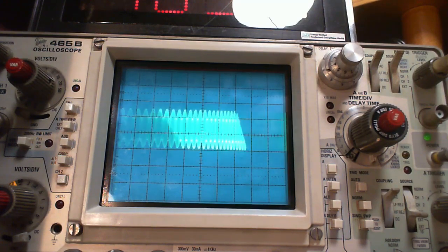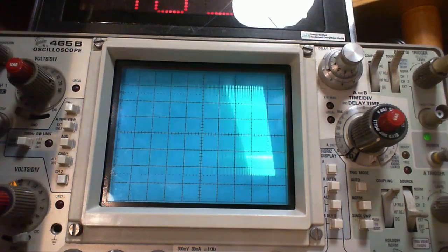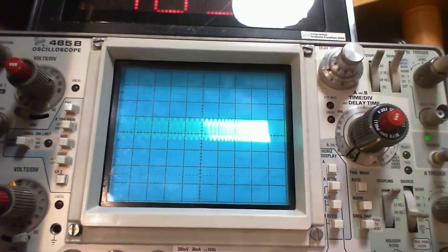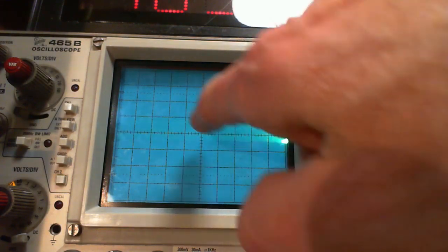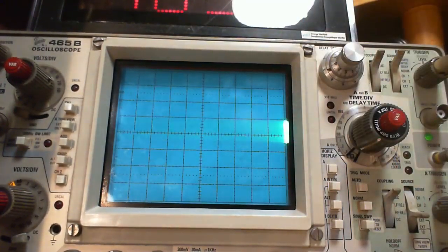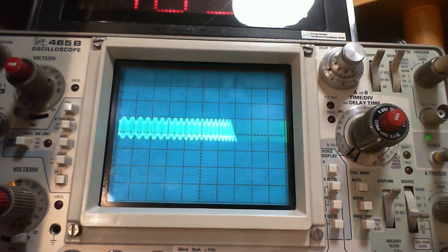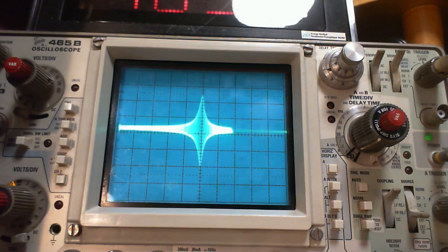Let me see if something really funny happens here. This isn't at all what I expected to see. Something funny going on here, because this frequency is not changing. You can hear me changing the band switch on the big signal generator. I'm putting in a wildly different frequency. It's exactly the same. I think that's a hum. How am I going to figure that out? And why would there be a hum?